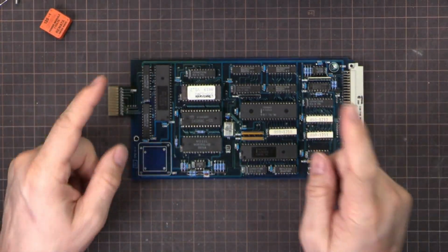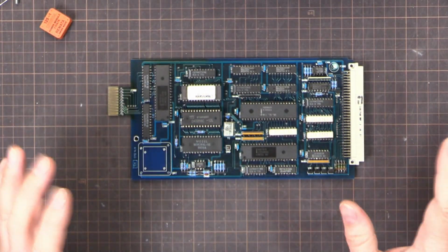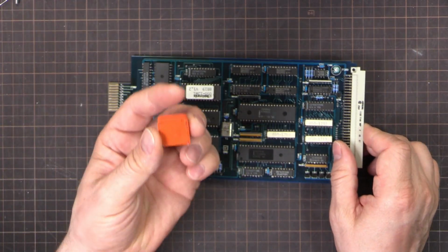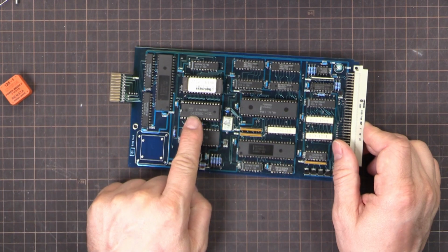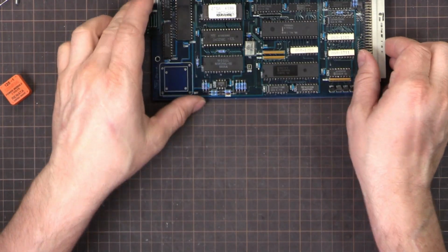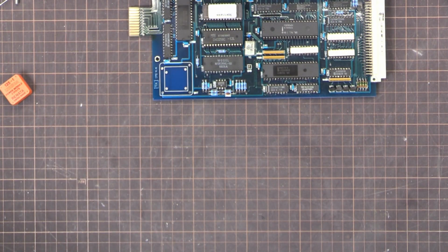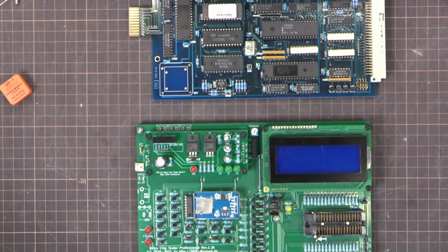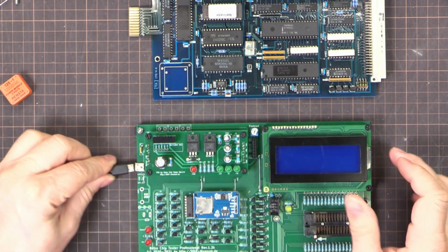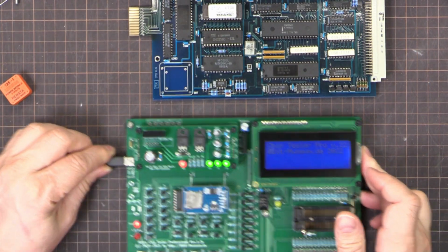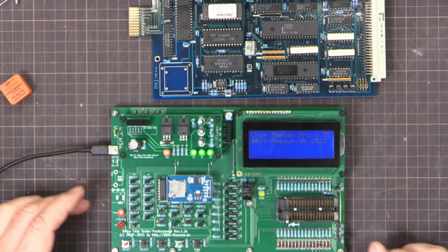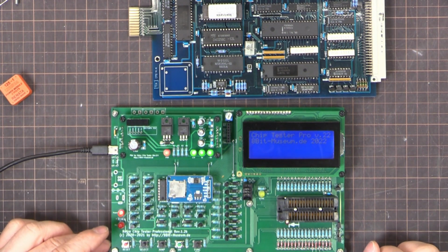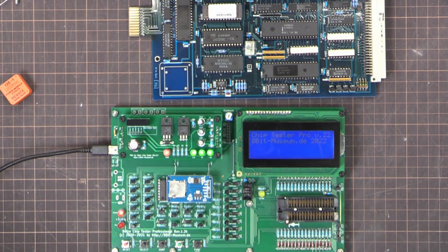Now, as for this other stuff, the RAM error, that could be because of that. It probably is because of that, but one of the RAM chips here is socketed. So, why not give it a test? I've got my retro chip tester here, which is fantastic. I use it all the time for testing 7400 series chips. Chip Tester Pro from the 8-bit museum. Fantastic stuff.